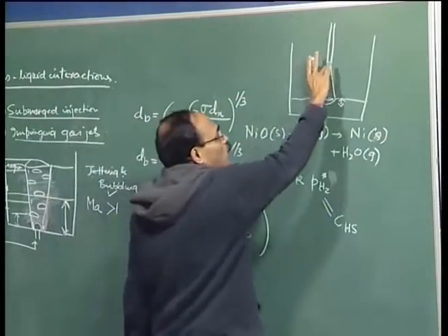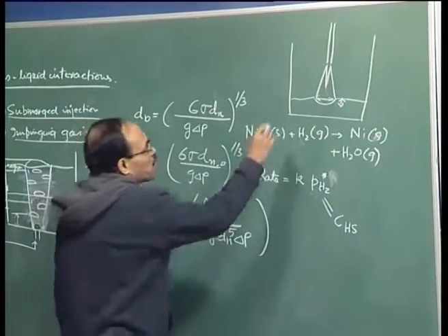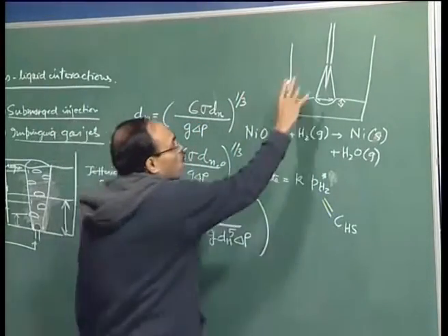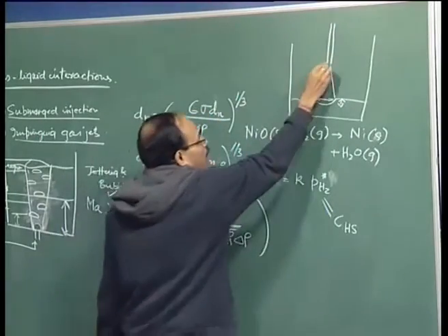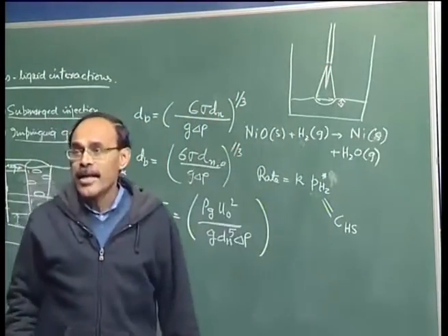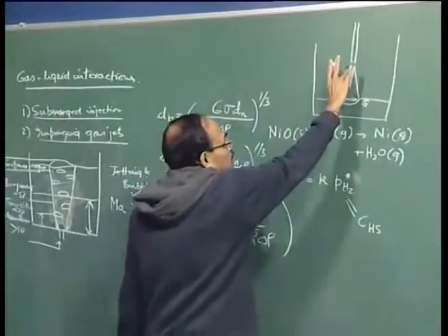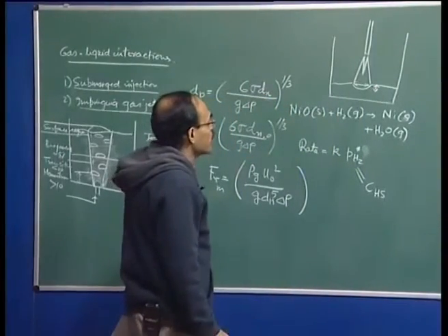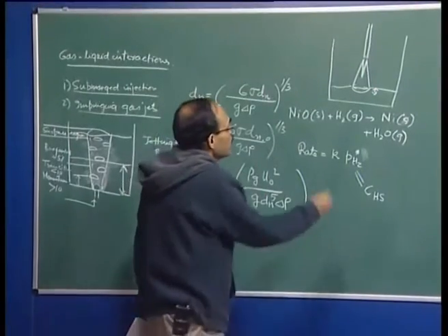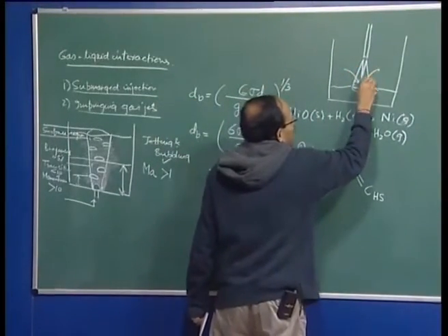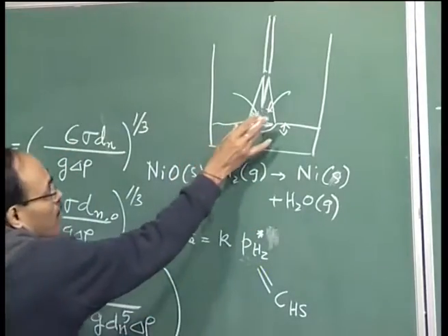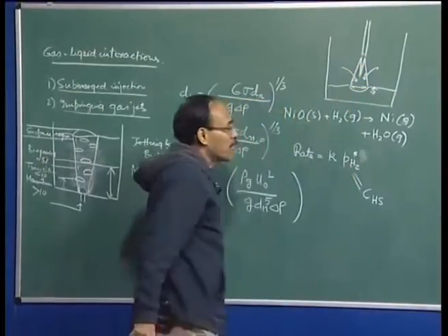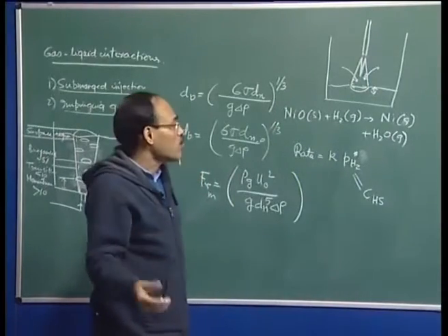The core is very, very important to us, and this core is about 3 to 8%. And what is this core? This is the supersonic core of the jet, and this core is 3 to 8% of the jet nozzle diameter. There are technologies available today, like the CoJet technology, which can enhance the length of the potential core, the supersonic core of the jet, to a significant extent. But beyond the supersonic core, you have large scale entrainment, as a result of which the jet diameter increases, and once the jet diameter increases, its momentum gets distributed, and by the time it strikes the molten metal surface, its kinetic energy has died down significantly.